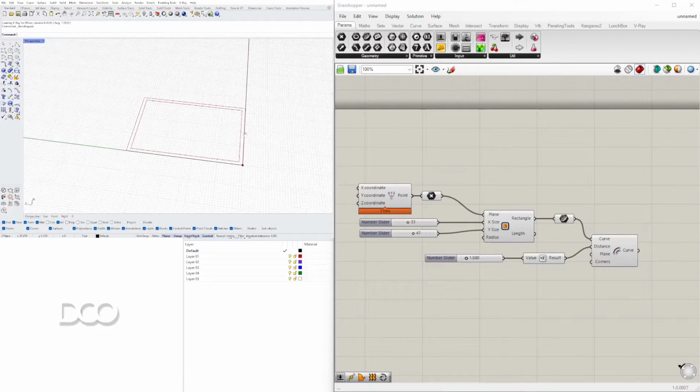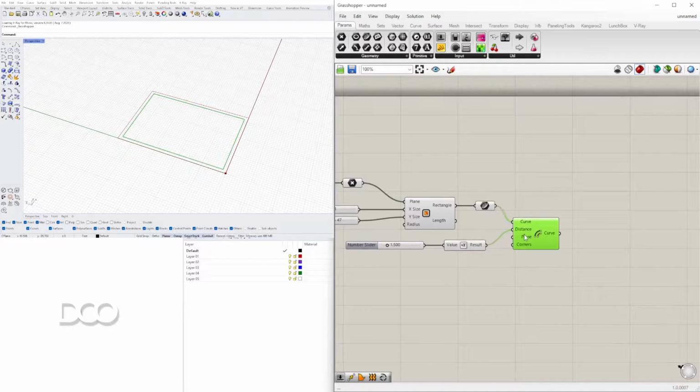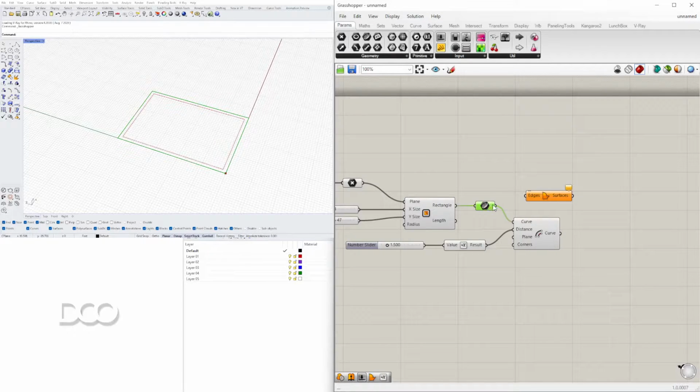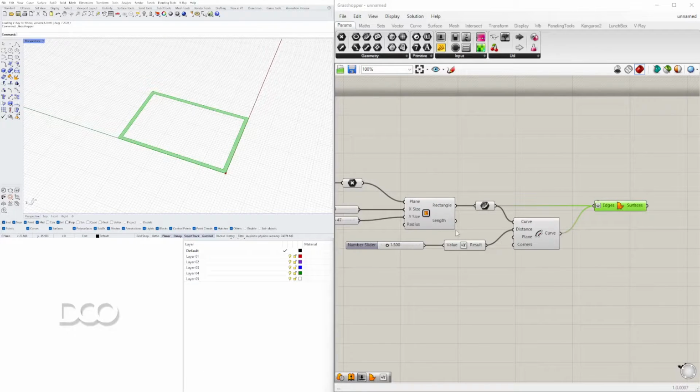So this is going to be the outer band. And we are just starting with the base geometry, so creating the outer band. And then on the inside, we can also subdivide it in different ways. But for that, we are going to use a particular design. On the outside, we'll just be creating a band that has subdivisions on the outside. So for that, we'll need to create a surface here and then a surface on the inside. So let's go here to boundary surfaces and plug in both the outside and inside one, holding down shift to add another one, and then we'll flatten the input. This way we have that outer band and it creates a surface between those two lines.